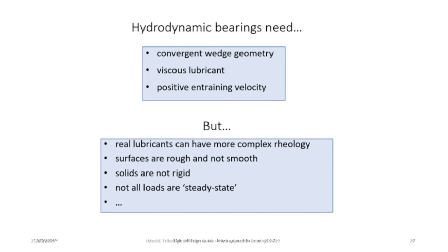Real component surfaces can never be perfectly smooth, but must have some roughness, and this might be of the same order as the lubricating film thickness. In other words, the lambda ratio approaches the value 1. Real materials are not infinitely stiff. Under high enough pressures, their surface profiles can change. Although this is unlikely to occur in conventional journal bearings using metallic materials, it may happen with softer polymeric components. This is the regime of elasto-hydrodynamic lubrication, and again there is guidance to these more advanced ideas in the suggested literature.